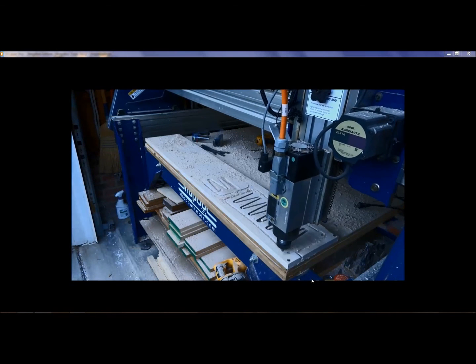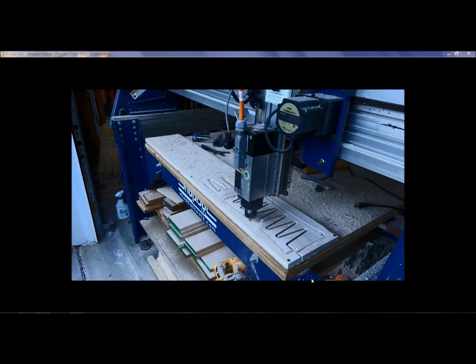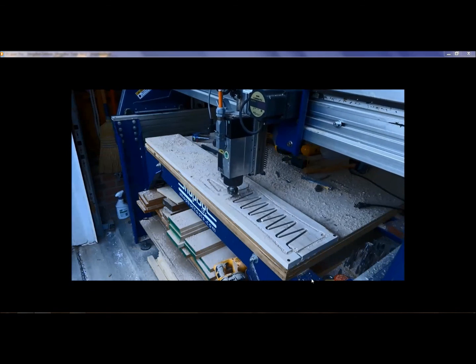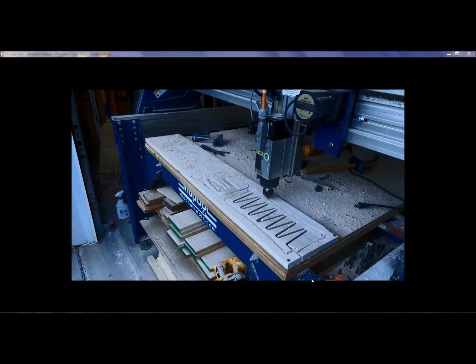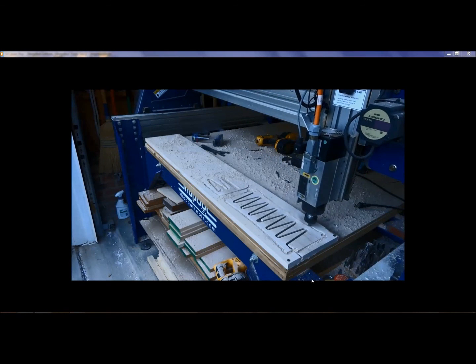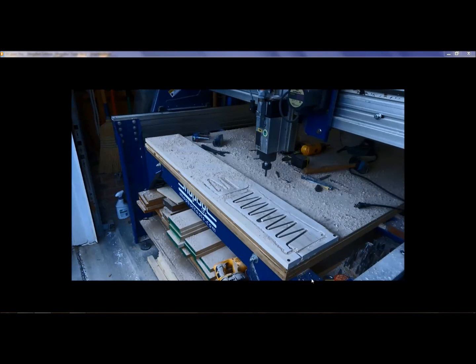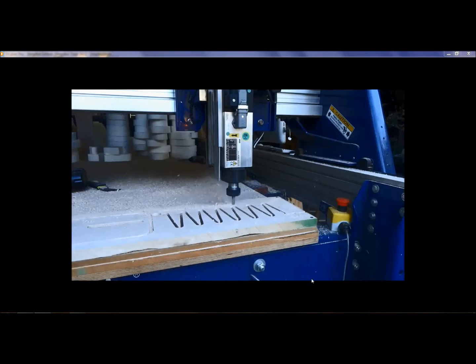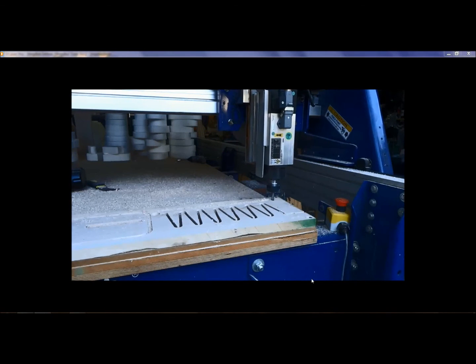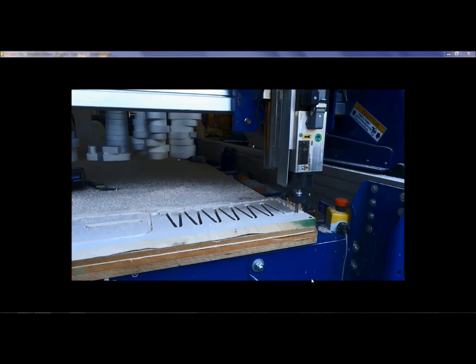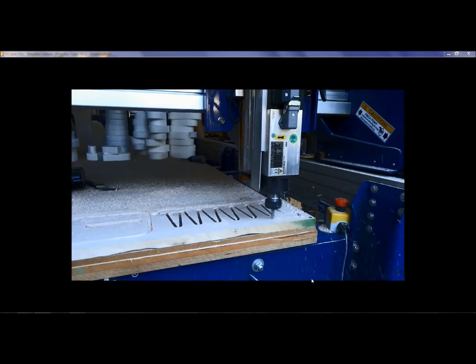So as it goes around, it now picks up for the tabs, and then it moves itself around and ramps down in the Z per pass. When I get done, that picks up, and before you even unscrew this thing, you're going to want to make sure you cut all the way through. But let's just take a closer look here.